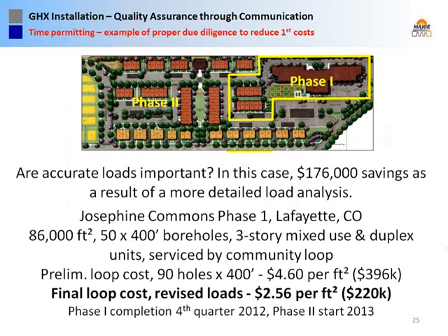Anyways, we noted that their cooling load was extremely heavy, and they were doing everything they could to minimize outside air impact. What we found was by running a load calculation with lower efficiency windows and slightly lower efficiency wall insulation, we actually balanced the load out, and that allowed us to drop from 90 holes to 50 holes by 400 foot, and it lowered the first cost on the building construction because they were able to go to a less expensive window glass.